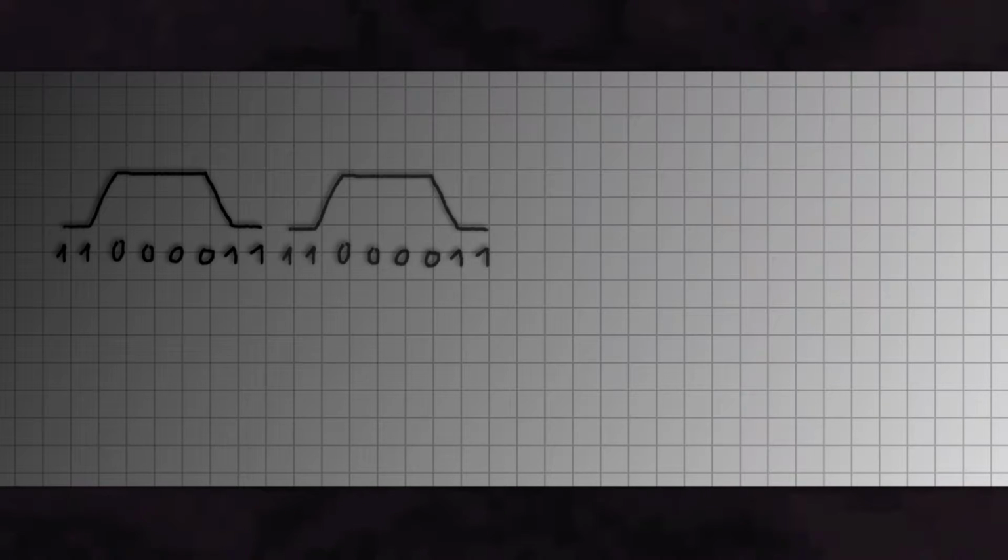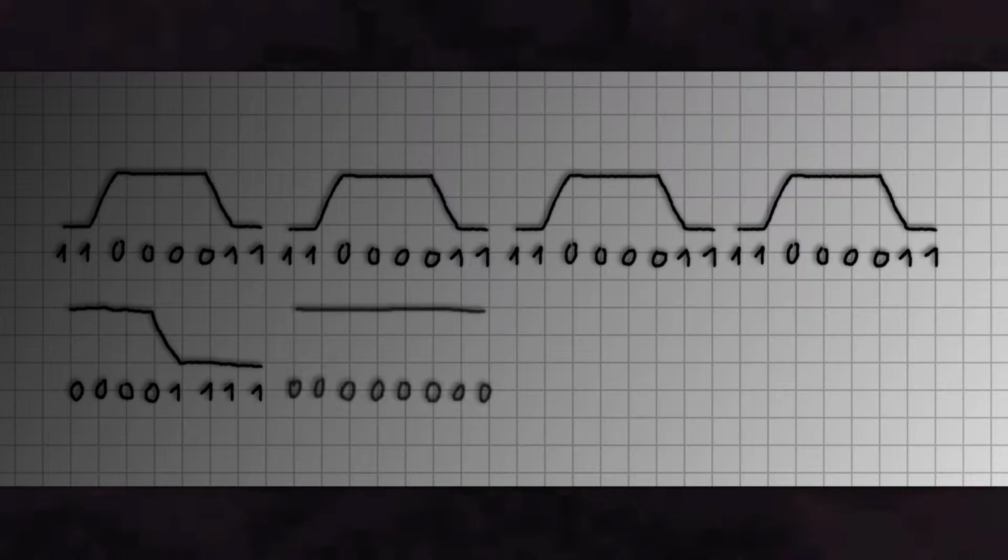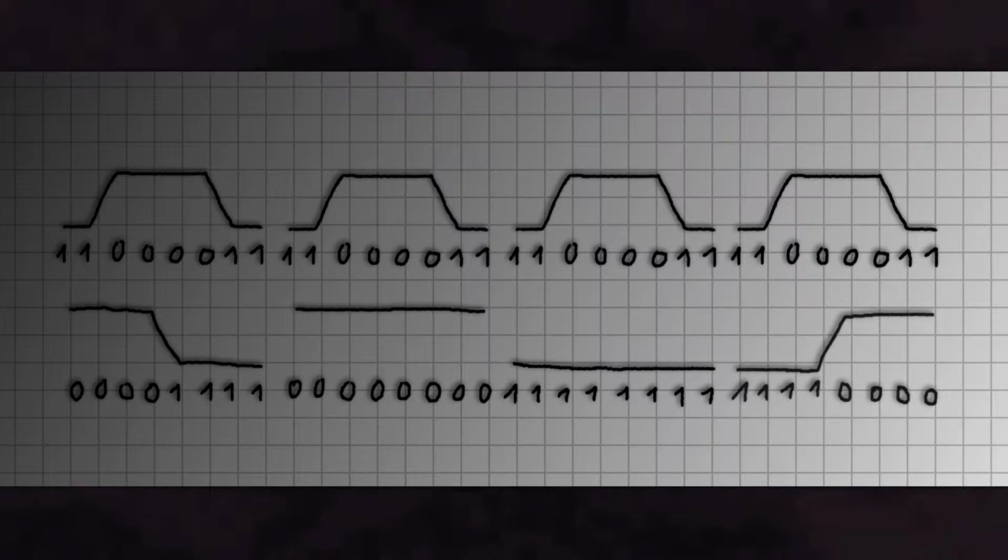So basically what's going to happen is that for every possible clock or data line pattern, I'm going to define a bit mask. To compose a message, I select the cycles that I need, depending on the datasheet of the device I want to talk to, stitch them together, and iterate through the message at an 8-bit per cycle resolution. In each frame of the program, the signals are then forwarded to the GPIO pins. The plan is to operate multiple master and/or slave nodes on the same platform simultaneously.